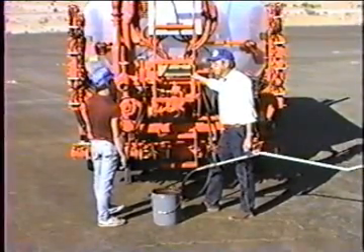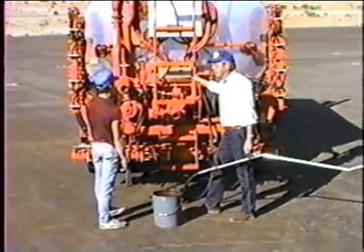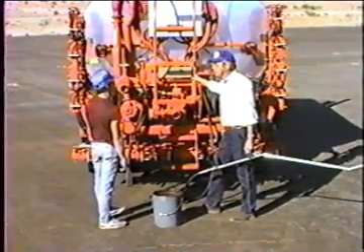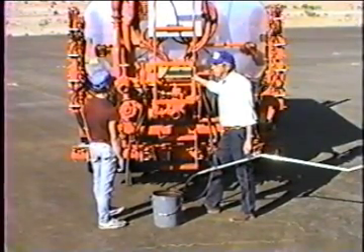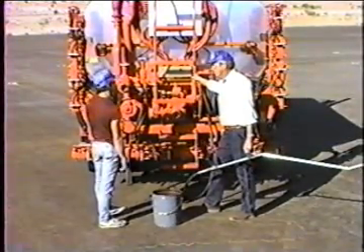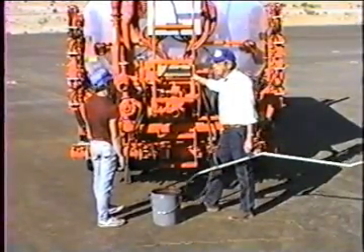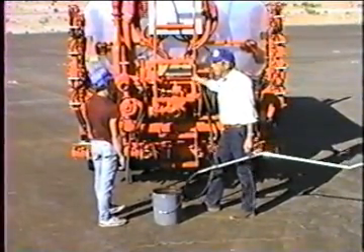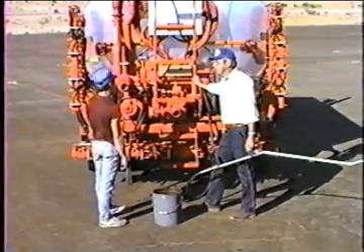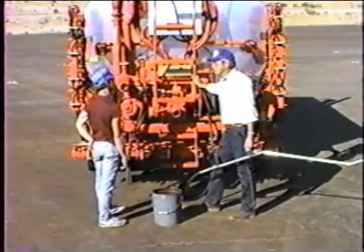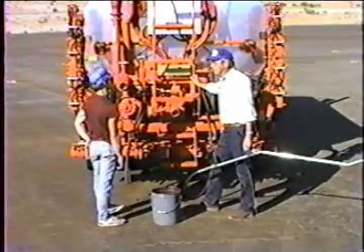Nearly any asphalt product that we spray with this truck can have diesel put in it with no harm. In fact, many of the products that you use already have diesel or kerosene or stove oil in them as a solvent in order to thin them down, just like a paint thinner. The only asphalt product that has no diesel in it is when you are spraying paving grade asphalt. And if you're in a particular area, primarily a state where they sample the product and test the product, then you want to be very careful about putting diesel into a paving grade asphalt.